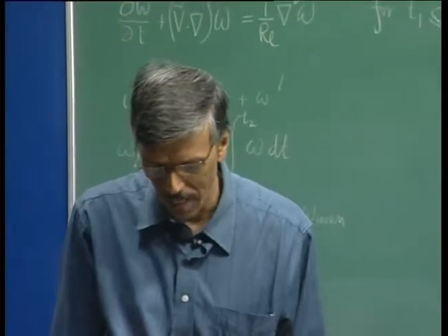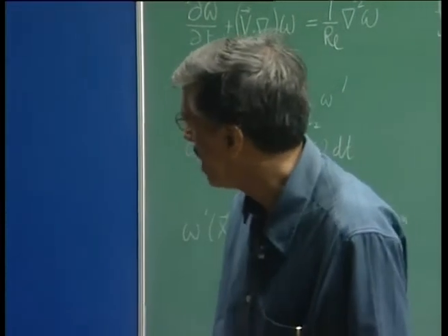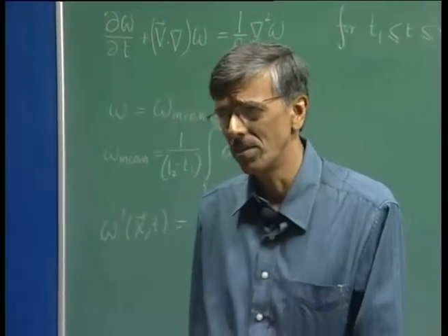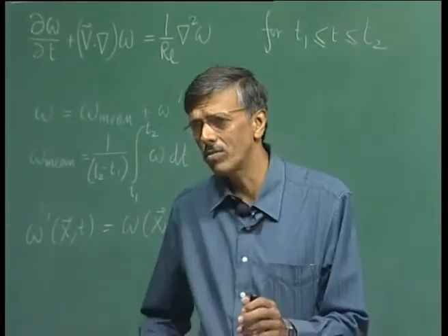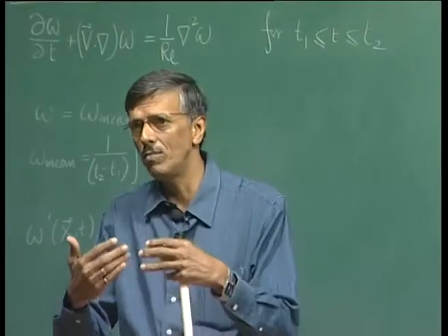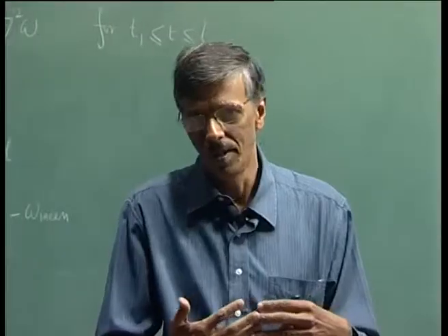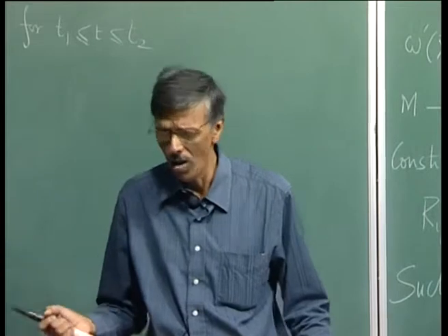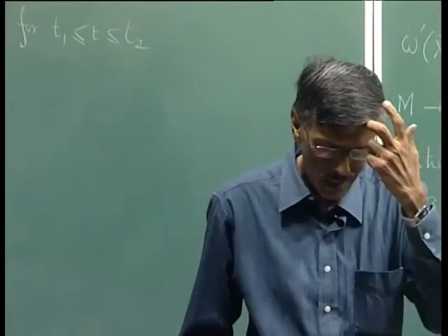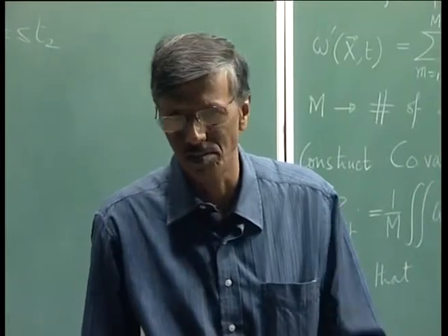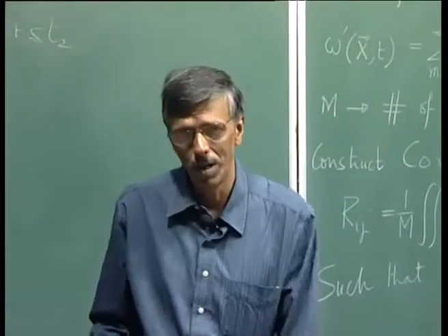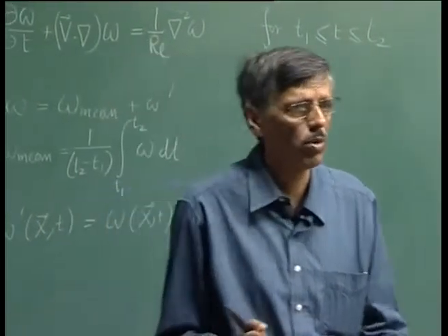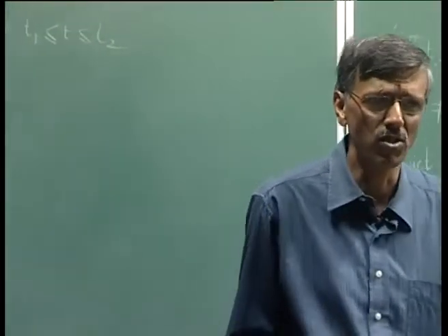Historically, the early practitioners of POD in this particular field, especially for flow past bluff bodies, noticed that you get these eigenfunctions occurring in pairs, and this pair formation is quite significant. However, sometime in the early part of this decade, Noack and his group from Germany discovered that talking about this modal behavior in terms of these pairs is not adequate.